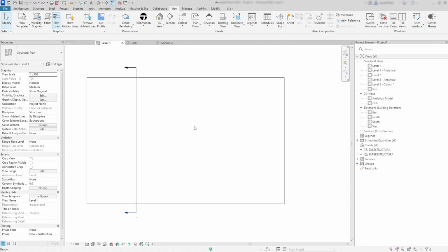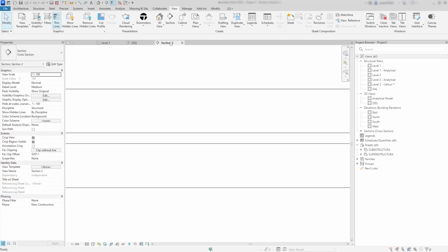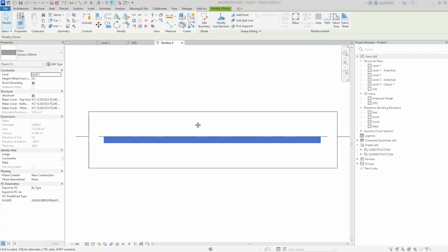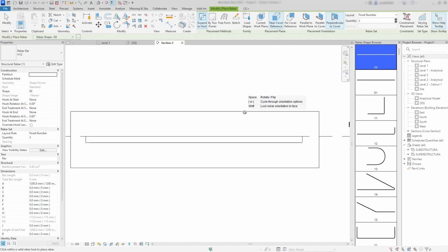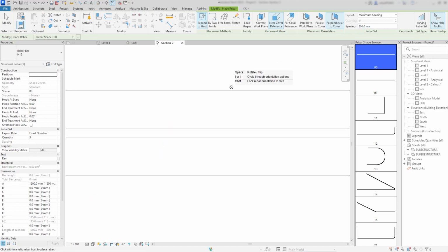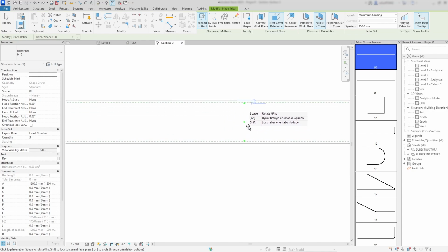and the tag. The next improvement has to do with reinforcing bars for concrete. Revit has been taking the construction process into account more and more, and in this case, it allows us to create splices easier than before. For example, I have a slab here to which I am going to add a group of rebars every 200 millimeters.